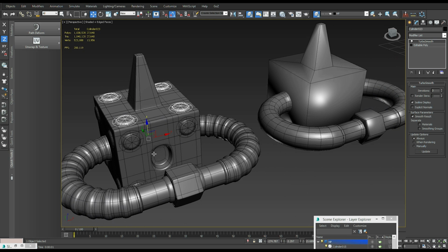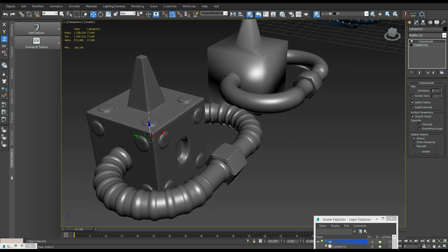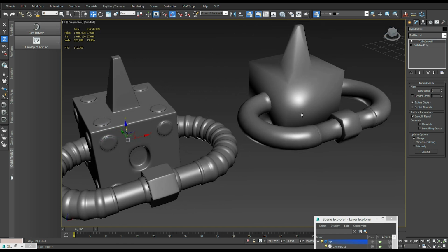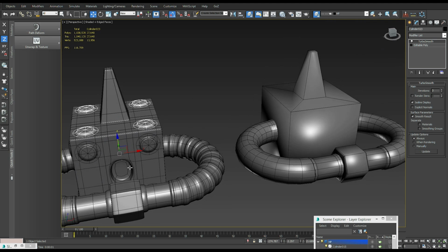If you look here, you can see what I've got going on. We have an area that's been extruded into the high poly mesh, but I really don't have anything over here on the low poly mesh. This really isn't a tutorial on modeling, but since I have it all here, I might as well mention it. Anytime you're going to be doing something like this, you want to bevel the edges inward, just slightly. Same thing if it was extruded outward. You want to taper those in.